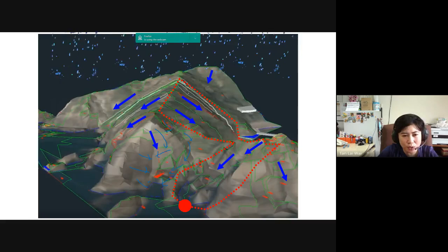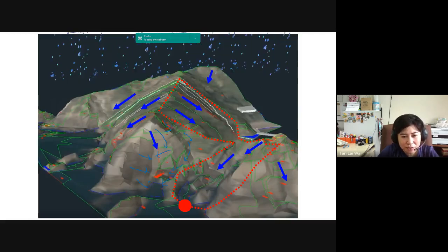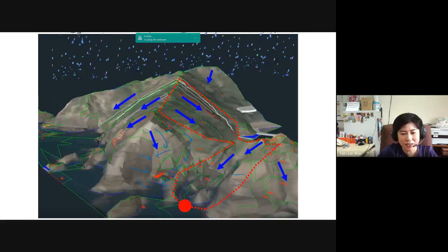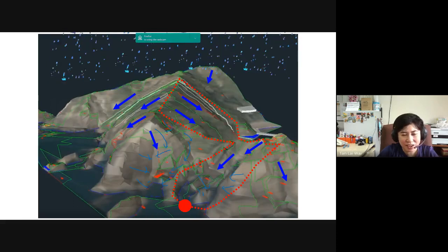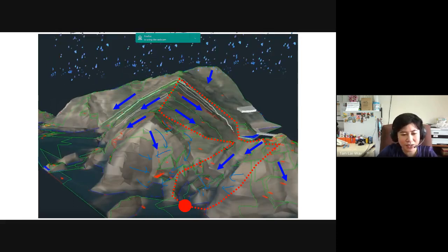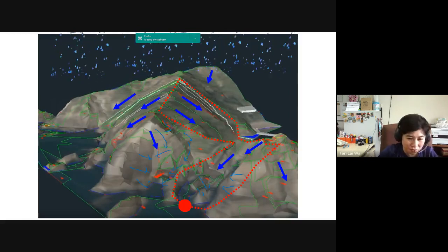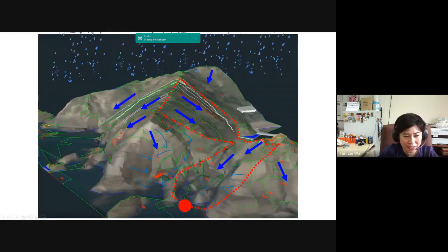So I imagine only this area, that when rainfall touches this area, it will be drained out from this outlet here. So it will go like that, it will drain out. So this dashed line here is my catchment area, and I need to find this area to use in the rational method. So far, are you guys clear?